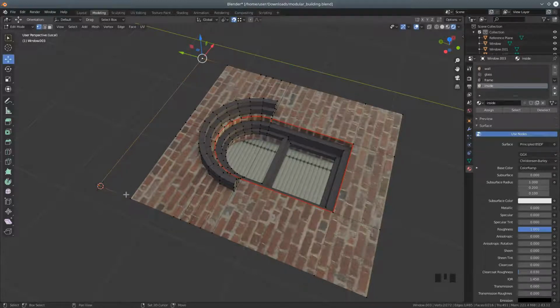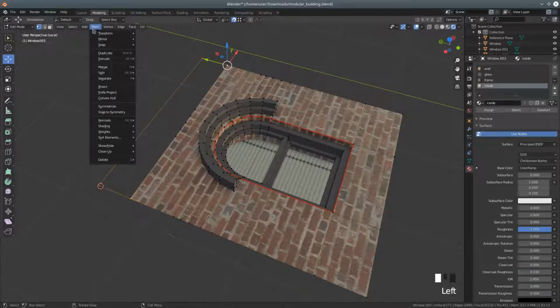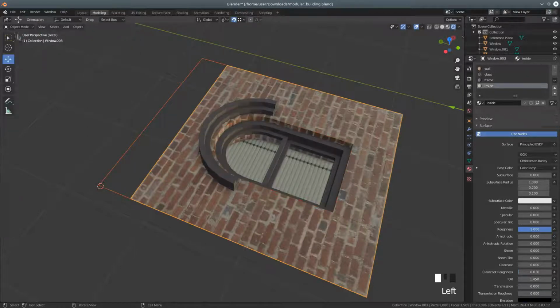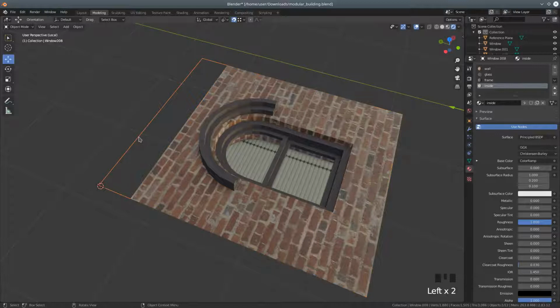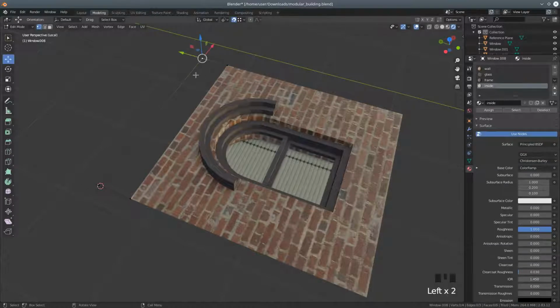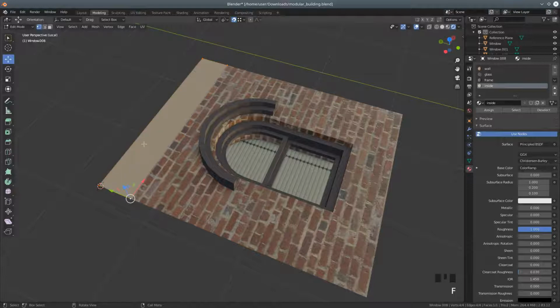Then I'm going to select this vertices and that vertices, and I'm going to say mesh, and we'll just separate that by selection. So that has made a new object, which we can then select in object mode and go back to edit mode. So let's fill this face. It's not a face yet, it's just 4 vertices. So press F to fill.